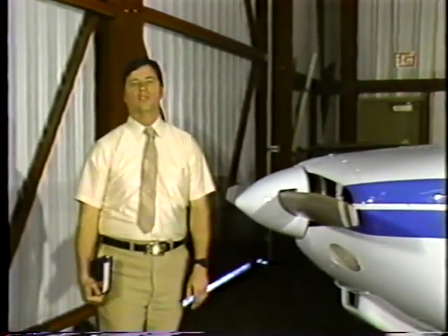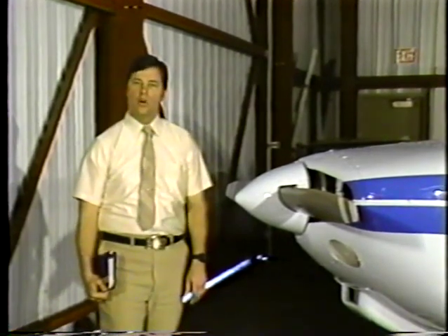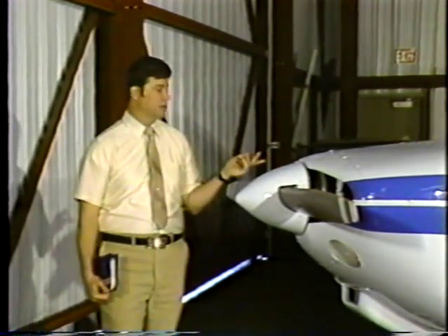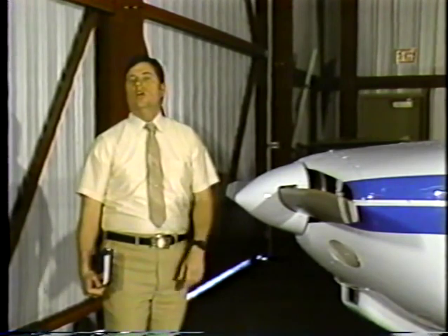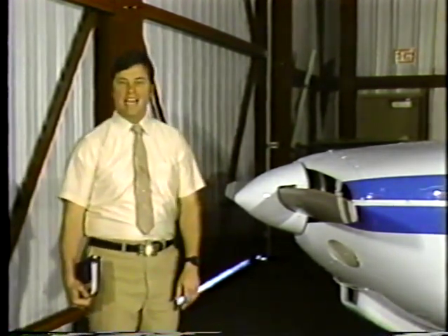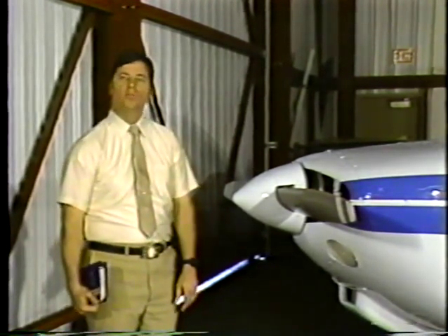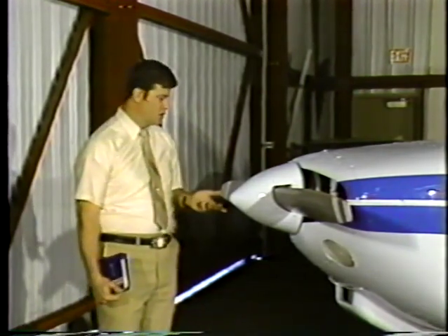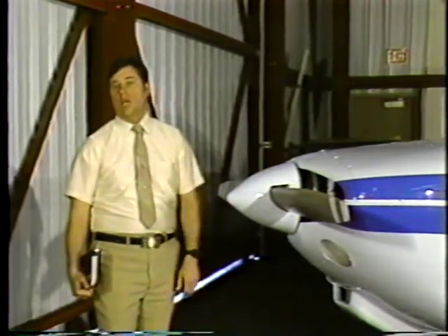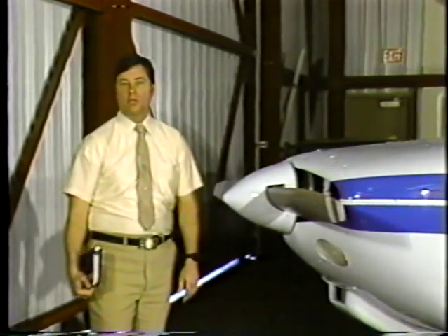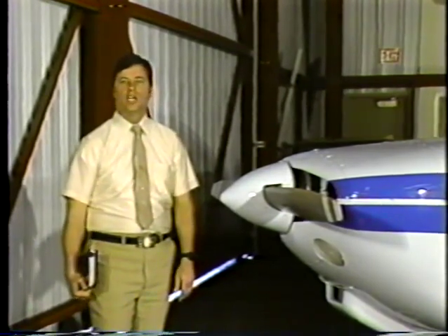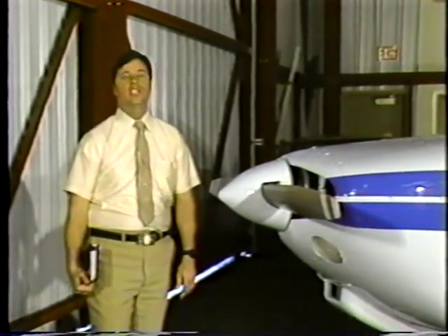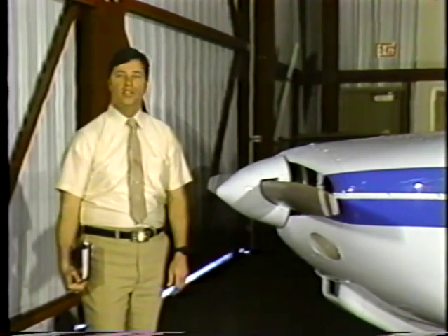To assist the pilot in his determination of the center of gravity location or balance point, the designer provides a reference point from which to measure the location of various weights loaded on the airplane. The point is called the datum or datum line. Most datum lines are located on or near the nose of the airplane, and for purposes of weight and balance computations, the plane is always oriented to the left. This makes these computations standard and easier to visualize.